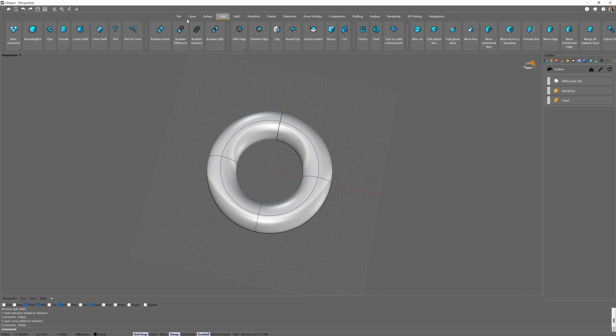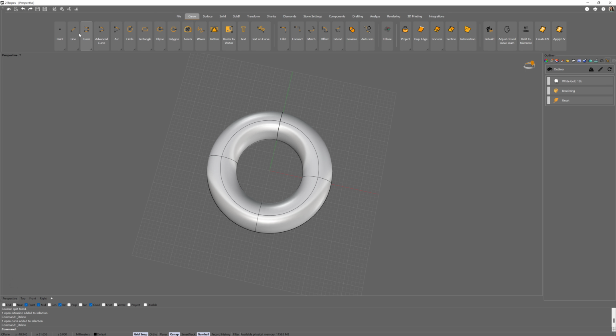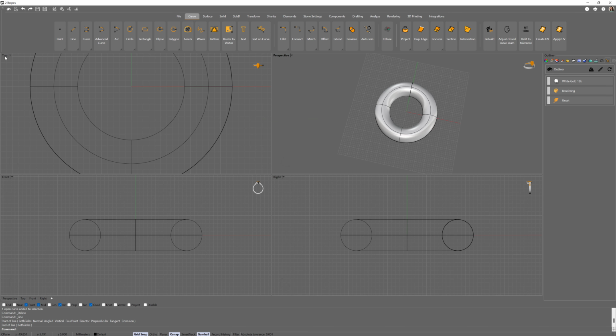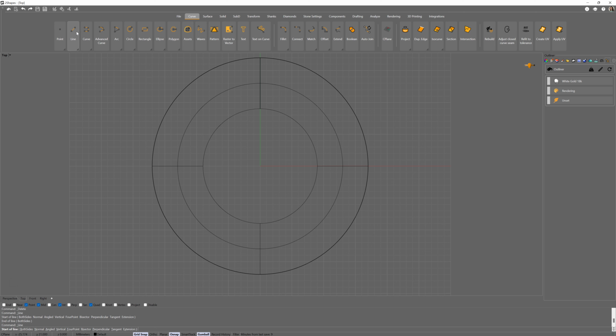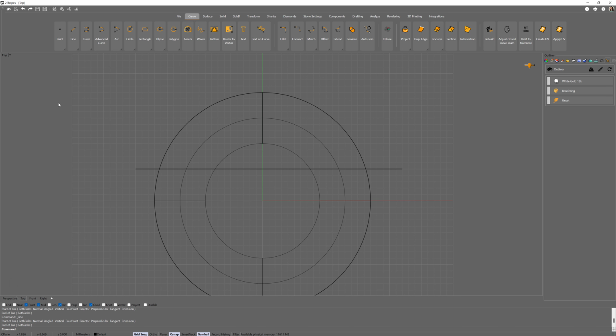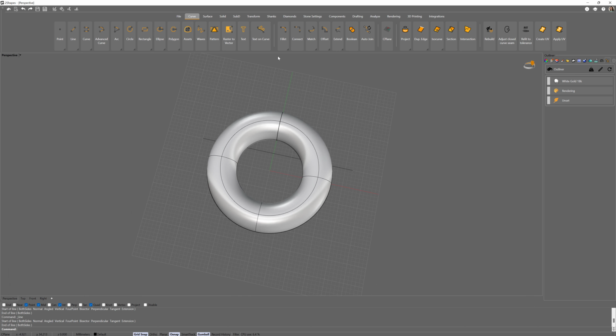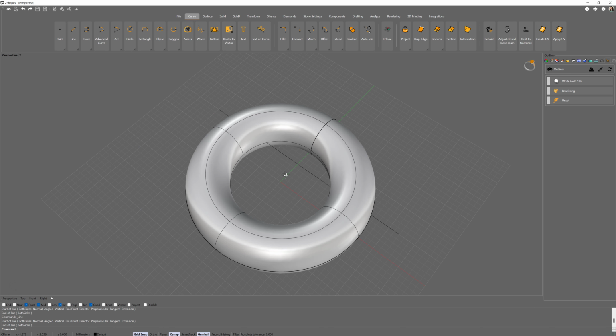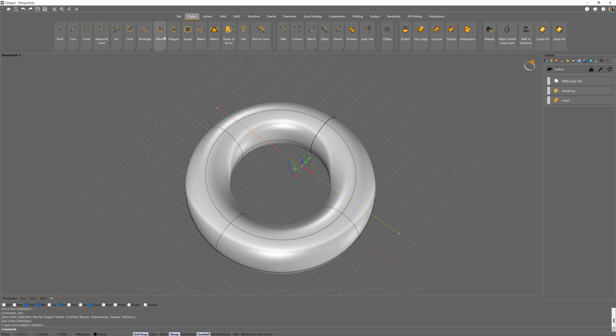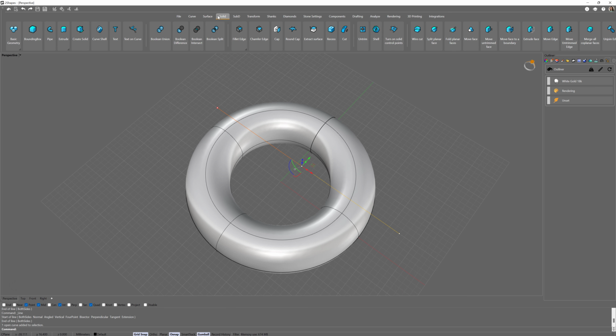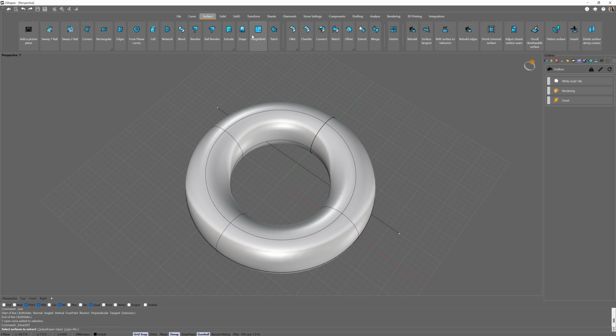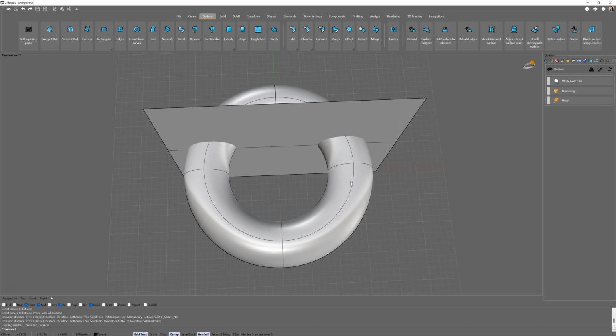Then my recommendation is, because it's thinking that you want to do a hinge to open two objects, one way that you can do that is just splitting the object before. Then you can create, for example, let me go to the top view. Any geometry is fine, even if you want to cut it in the small part here, but it must be two objects. Then now we extrude, we select solid and extrude, surface extrude. I always use the commands, and okay, now we have one torus.